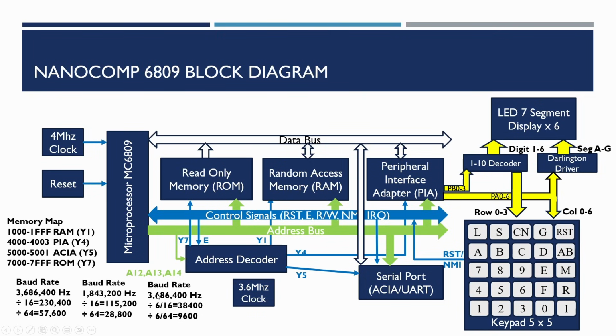So in order to do this dividing, a bit of an awkward number, divide by 6, but there is a particular chip, a standard logic TTL gate, which is the 74LS92. And that has built-in divide by 2 and divide by 6 on the chip. Divide by 6 or divide by 3 is quite awkward. You need a specific arrangement of flip-flops to be able to do that. But this chip already has it. So what we're going to do is use this 74LS92 with divide by 6.